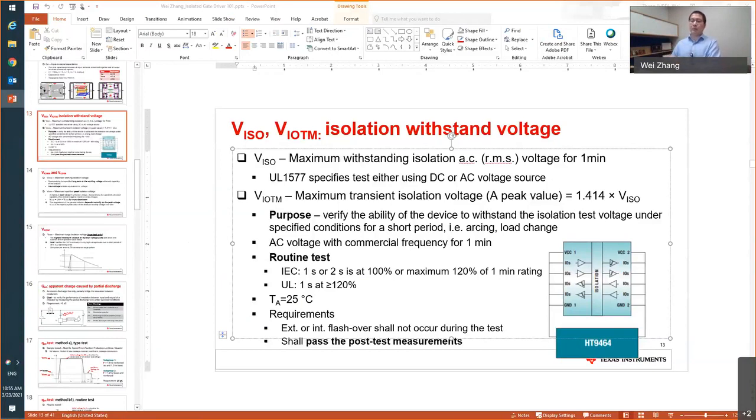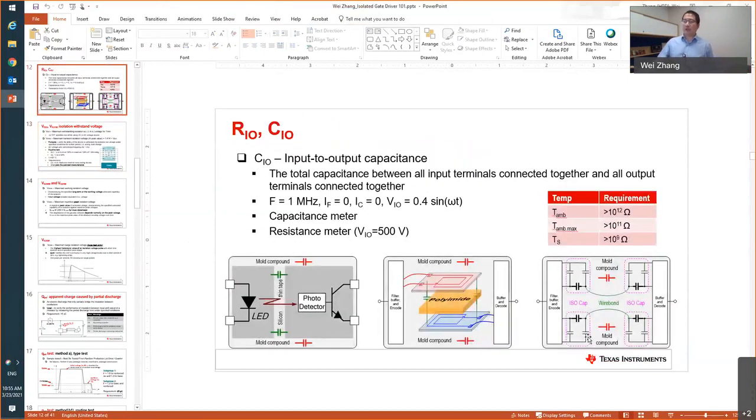a noise being coupled, but that's why you have a differential amplifier. If you go to this page, you have two differential pairs, and this is designed to block any noise from left to right on the common mode. Because when you have radiating noise, it's pretty much common mode. So we have very good performance there too.